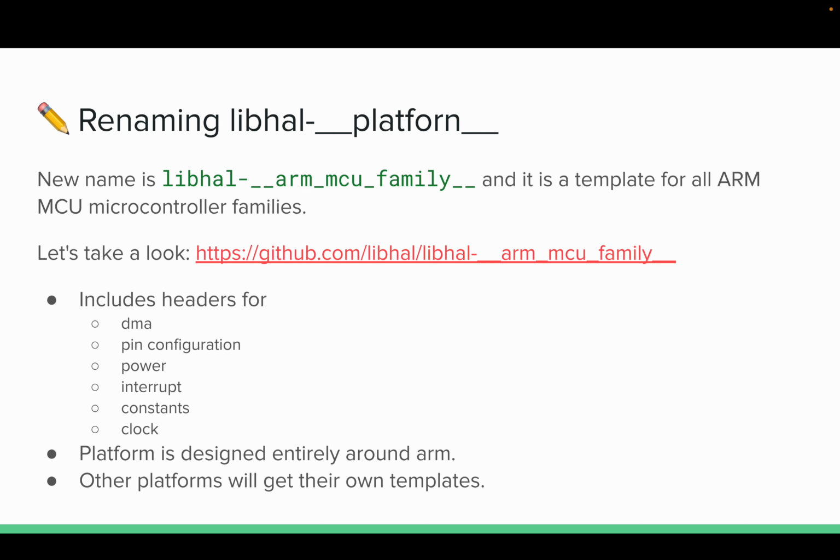So we use that to figure things out. The other two numbers here are not important for figuring out which memory layout to use. They are important for the chip size and what the chip may support, but it's not important for the linker script. So these are X'd out, and then there's a script, or part of the Conan file script, that will transform those letters into X's in order to map to the appropriate linker script.